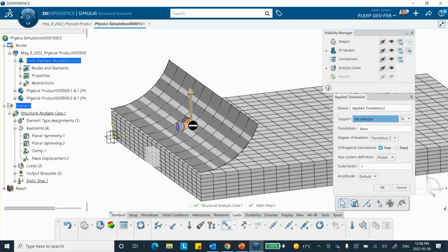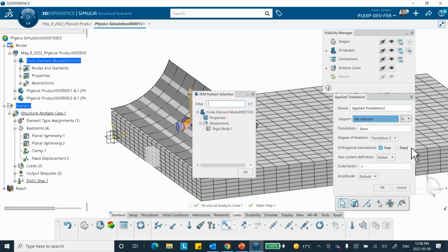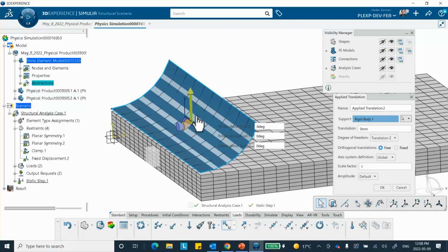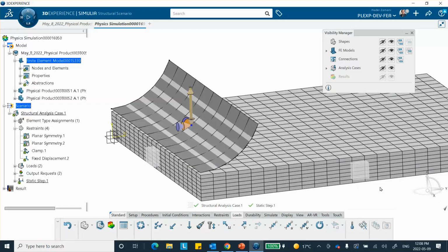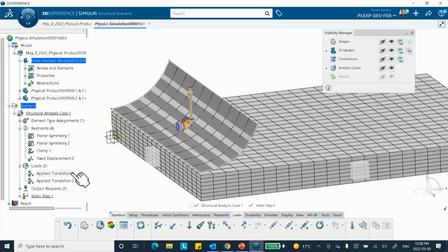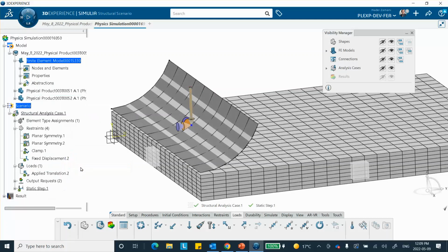to that point. Once again, if you're having issues with this, go to FEM feature, and there's the rigid body that you selected, and you give it a displacement in direction z of minus 0.4. There's two of them here. I can't see where the other one is coming from. Let me see. Inadvertently, earlier I probably put this one. Let me delete that. Right there.